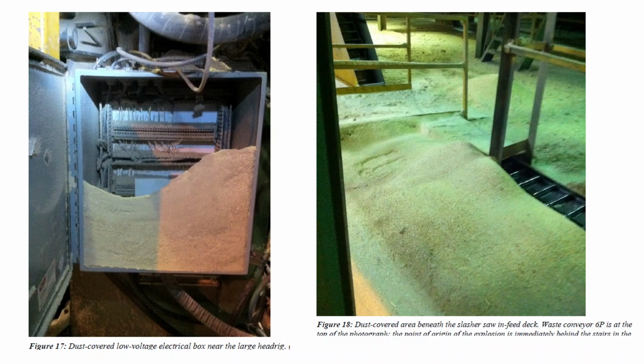And so what you can see is that there's a significant lack of housekeeping that's occurred here, where there are monstrous accumulations of dust. How on earth that control panel could even have that much dust is beyond me. I'm guessing there must be a few open half-inch knockouts at the top that just allow dust to pour in.